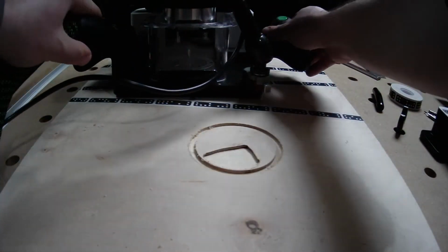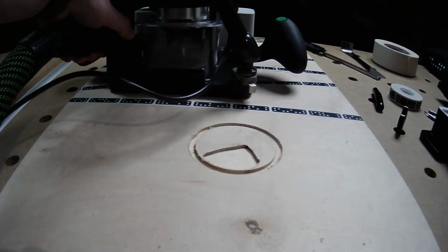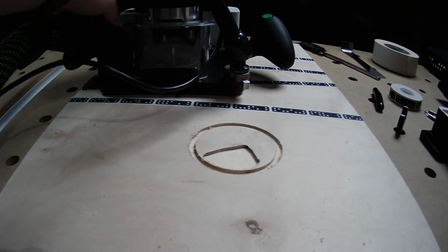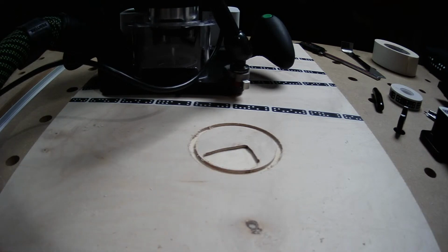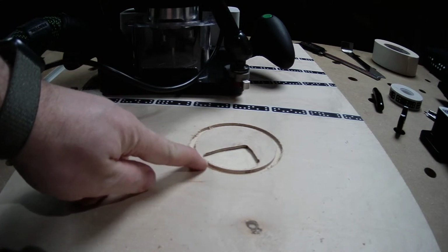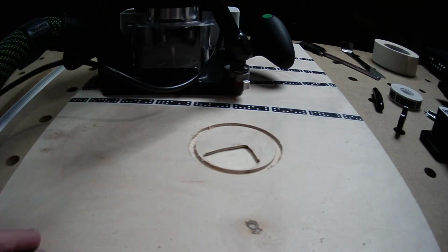Here you can see that's the part he removed. It's up to you how much you want to remove, but ideally you would remove it all, then change the cut type from pocket to inside, and then finish the shape. Pocket actually leaves a little bit of space on the outside so that you can change to an inside shape and finish it. Okay, so that's good. Thank you for that, Noah.